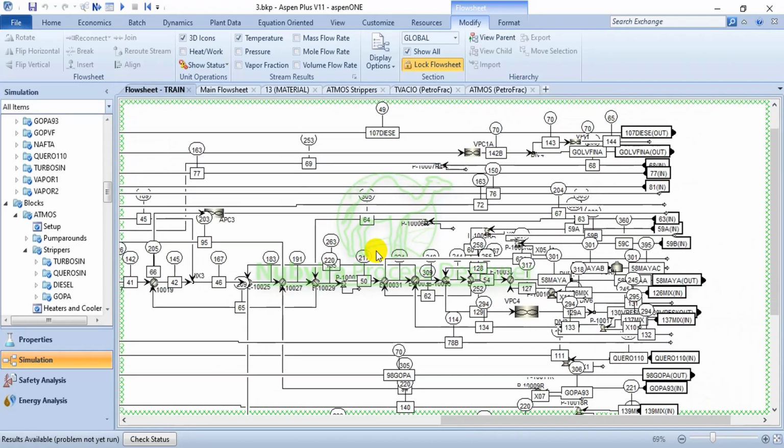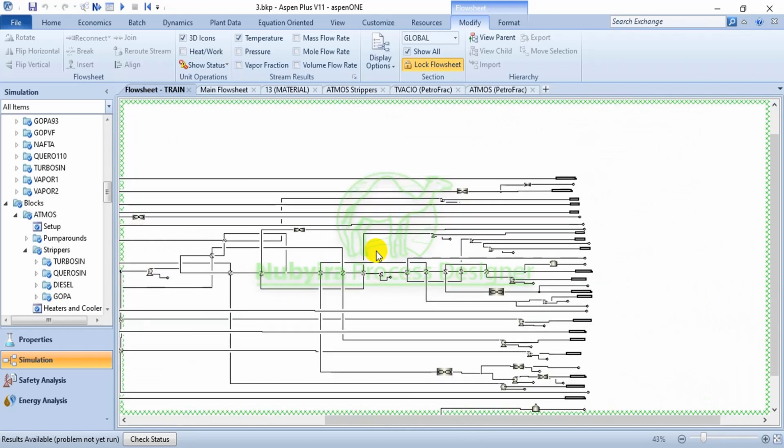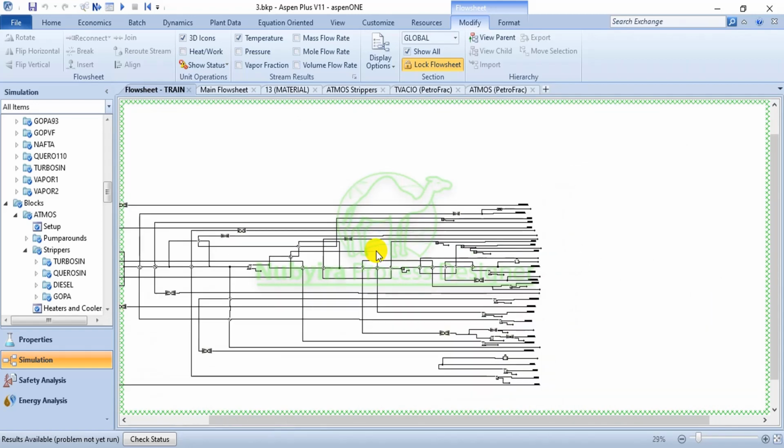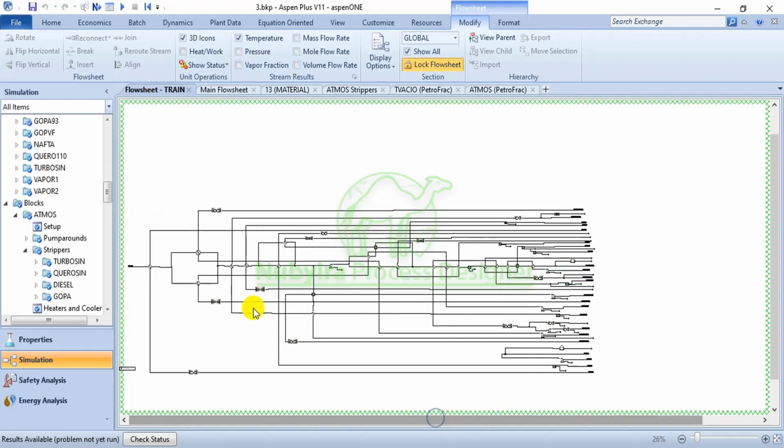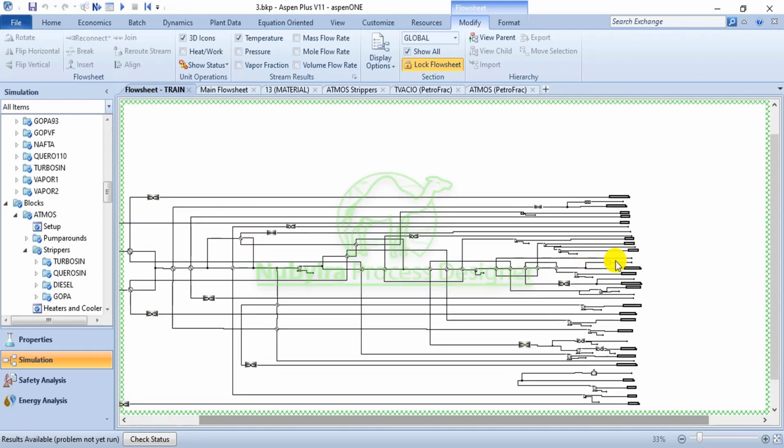You have a series of heat exchangers that are intertwined, connected with the product streams. Then we have the utilities, the coolers and the heater. For example, this is the furnace that has been duplicated in the heat exchanger network, and the coolers make sure that we are getting the product specified temperature,